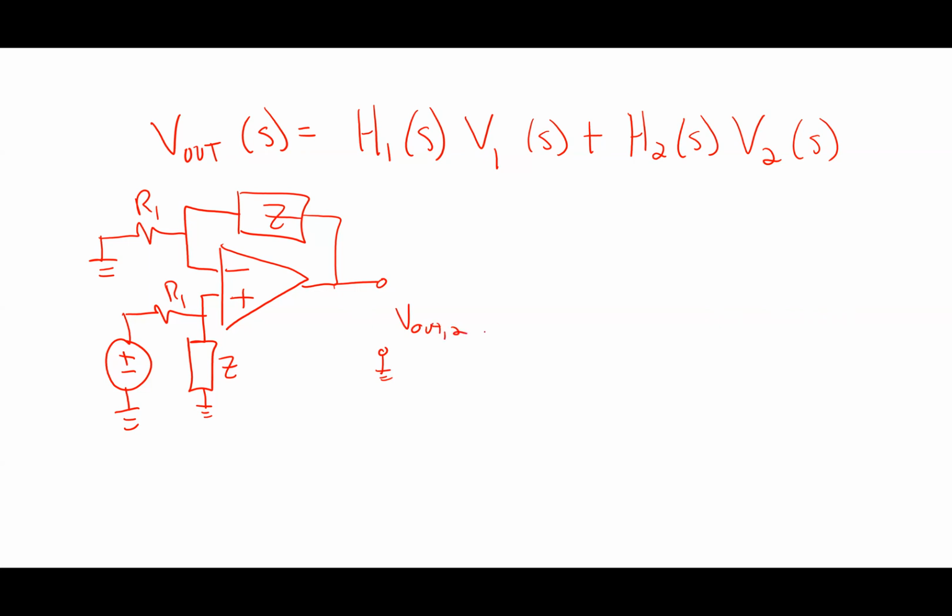Okay, how would I do that? Where do I start with that? We already did this problem. I had a voltage divider. Yeah, so V plus and V minus are equal to each other. One of the nodes is always easy to figure out. In this case, the one that's easy to figure out is pinned by the input voltage.